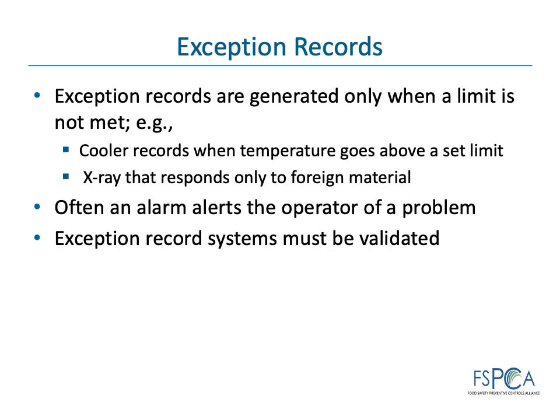Exception reporting involves automated systems that are designed to alert operators and management only when a deviation, in other words an exception, from the requirement is observed. Automated exception reporting may be more efficient than that performed by operators, allowing increased sampling frequency, often continuous, and reduction of human error. For example, refrigeration temperature control can notify on exception, e.g., high temperature alarm, and may only record temperatures that exceed the specified temperature.